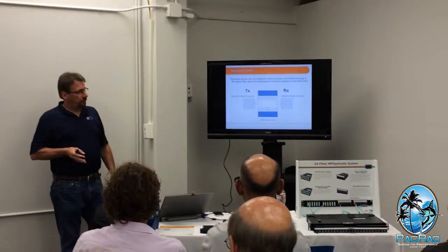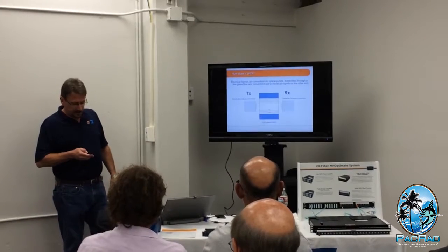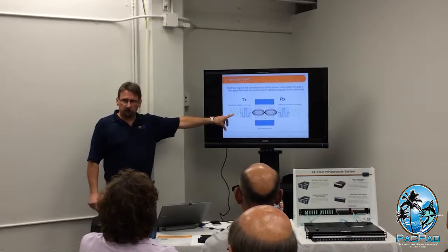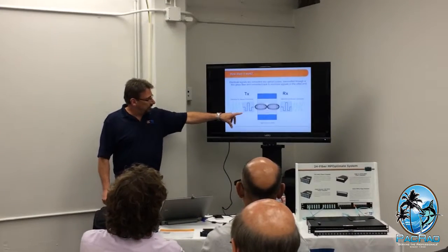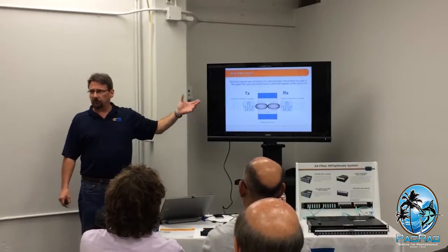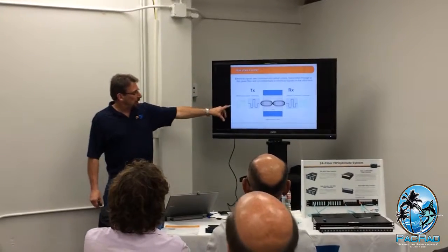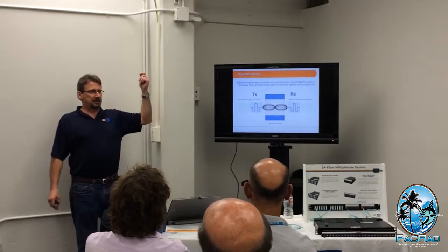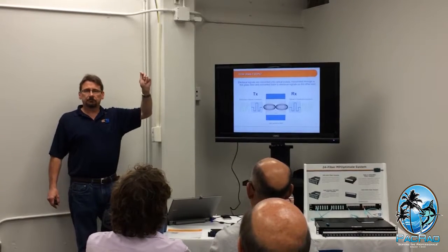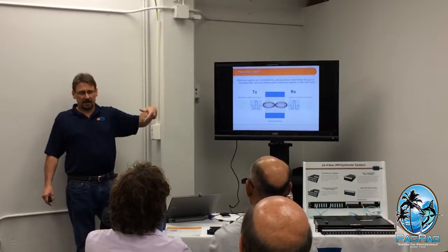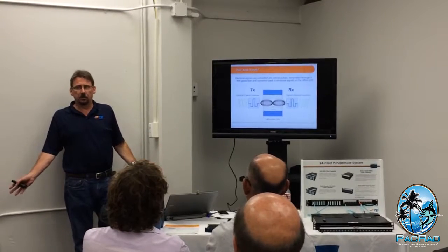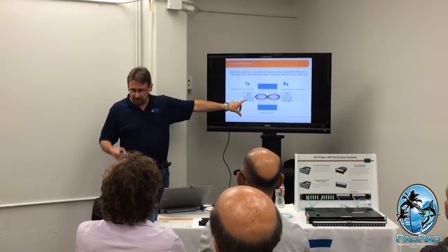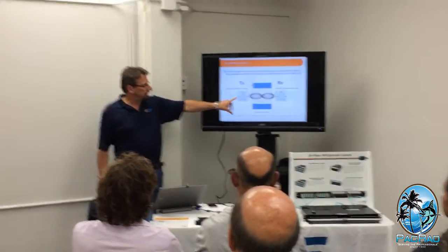Right, so how does it work? Well, it's not real hard. We take analog electrical waveforms and we convert them into digital optical pulses. All we're doing is signaling with binary code. We're taking a light switch and turning it off and on. Light there, that means a 1. Light off, that means a 0. Binary code, simple. How fast we can modulate that determines how fast we can send signal, or what bandwidth is.